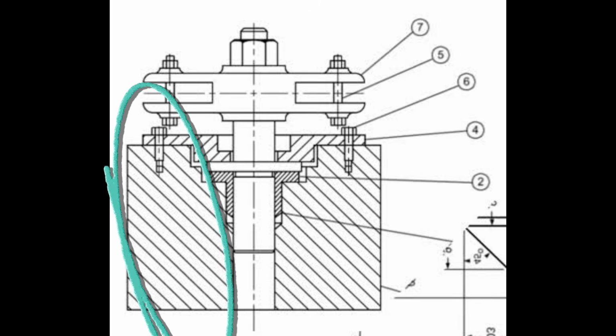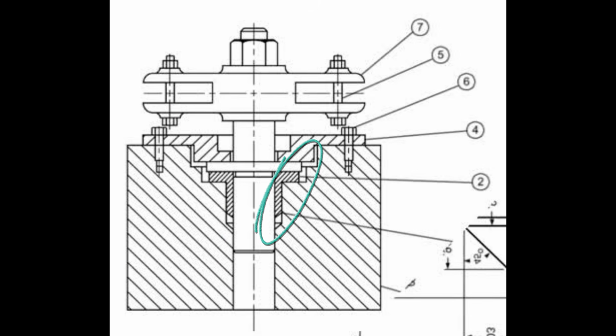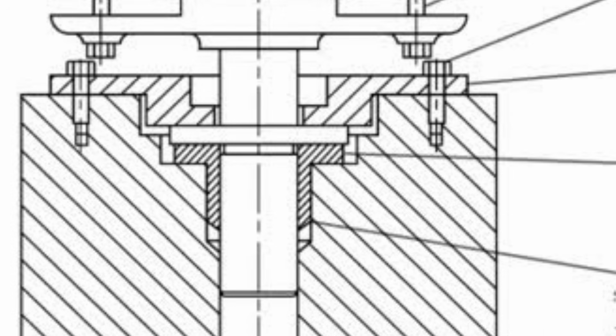The smaller the part, the closer the lines get. When two parts are next to each other or on top of each other, you always find that one cross hatching will be in one direction, and the other cross hatching of the separate part will be in the other. Only done at 45 degrees.